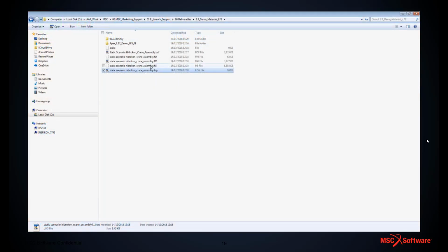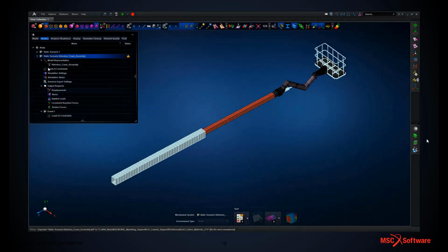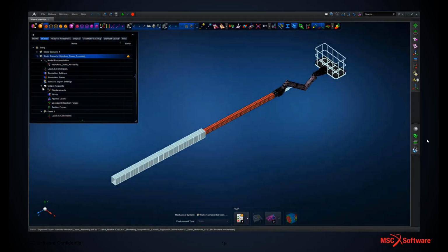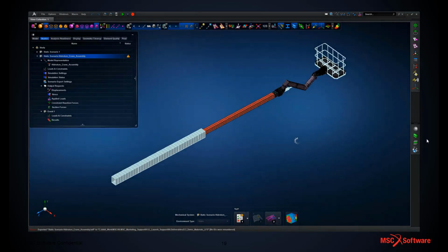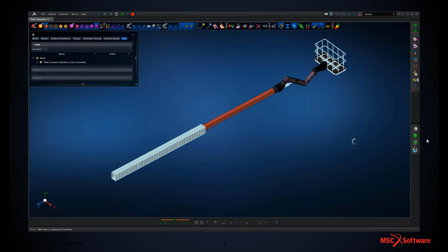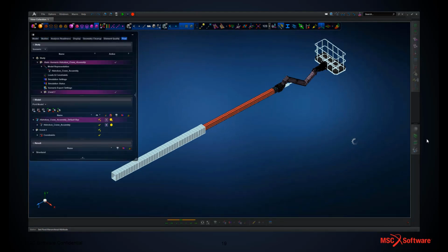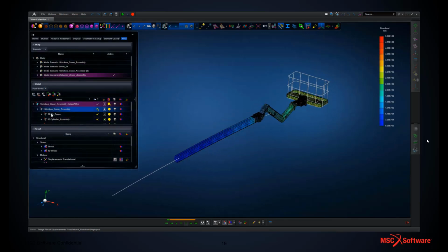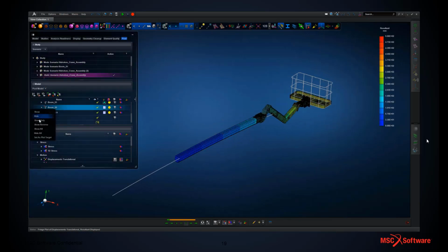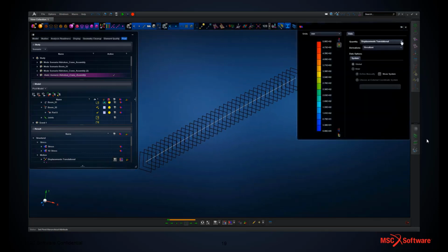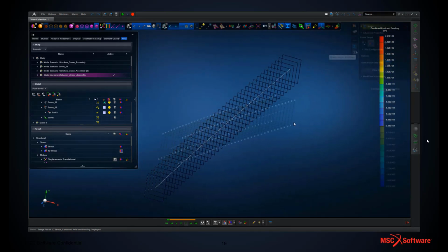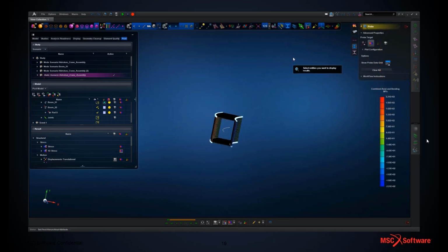We can run the Nastran result or generate the Nastran results externally, and then read that HDF5 file back into the Apex environment. Just bringing that in, importing the results, and the results are brought in successfully. We can now post-process. So we're going to look at a quick animation of displacement, and then we can look at discrete results. So in this case, we're looking at the beam element section outputs, based on the combined axial and bending stress, and then we can look at using the 0D cursor, so we can pull out discrete results.